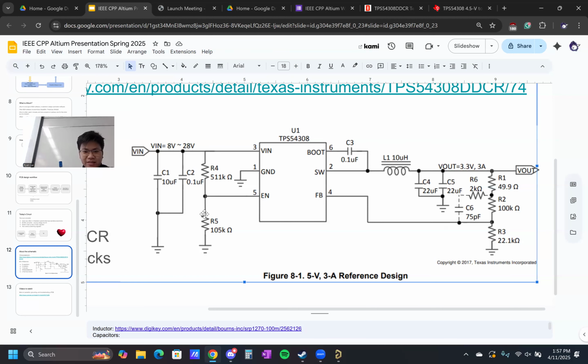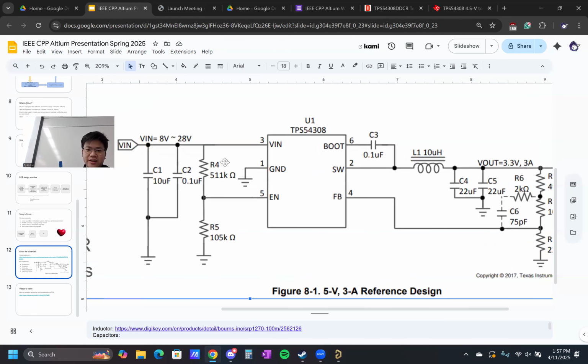Next we have this voltage divider circuit. I'll include you in the conversation. Yeah, I'm explaining what the circuit does. These capacitors are mainly for filtering noise. They're using two different values to filter different frequencies.